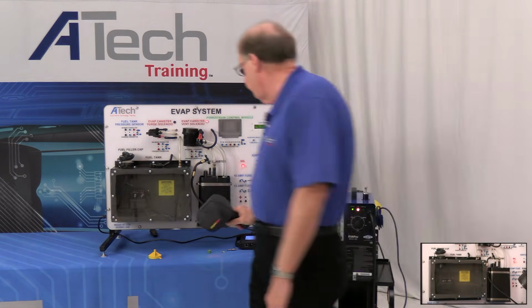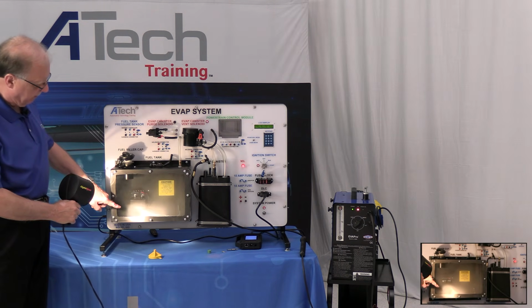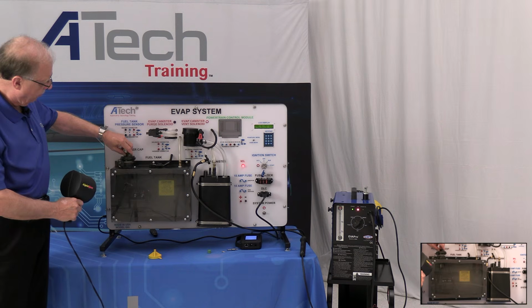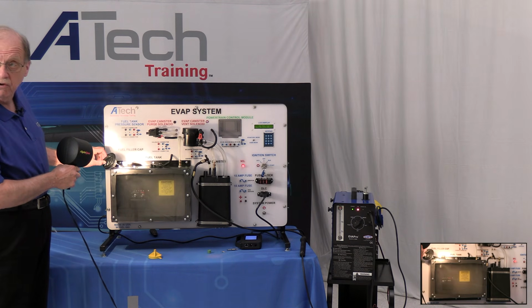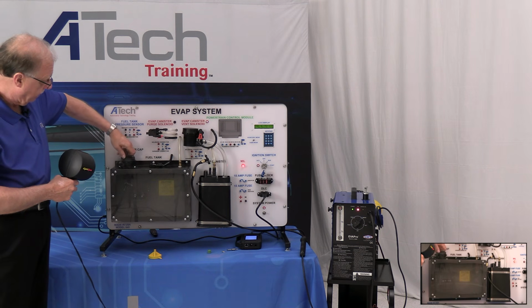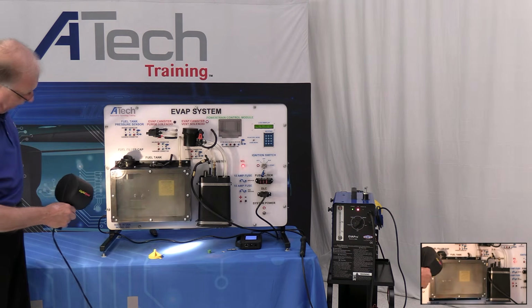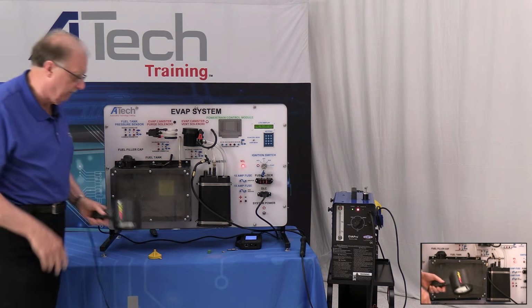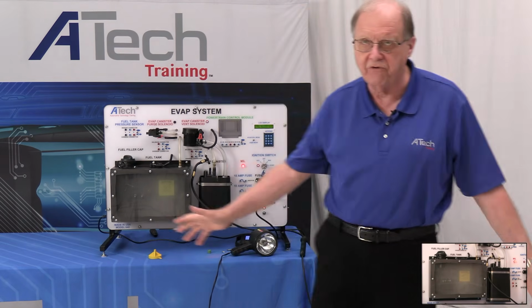Now I'm going to flip over to the other side real quick. If I'm looking at all the smoke, you notice the smoke is building up here. So the next thing you want to do, you look at the gas cap. You see the smoke coming out right there. First thing you want to do is close this thing off now. Make sure you get a good connection. And then you're going to go around the system to find out where the leak is. Now, I would tell you this might take some time because it's a plumbing system. You have to look at it.